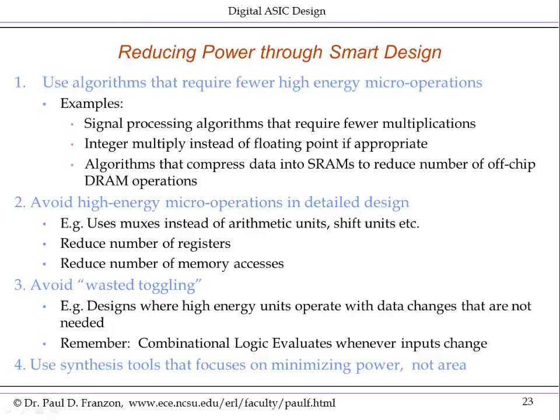So the question is, what can you do as a detailed logic designer that will improve power efficiency or energy efficiency? Well, one, of course, is to use algorithms that require fewer high energy micro-operations. For example, signal processing algorithms that require fewer multiplications or narrower multiplications. Do you really need 32-bit arithmetic? Can you get away with 20-bit arithmetic? Can you get away with an integer multiply and tracking the exponent rather than doing full floating point? A big one is, can you keep the data on chip, avoiding expensive DRAM accesses even at the expense of more SRAM accesses on chip?